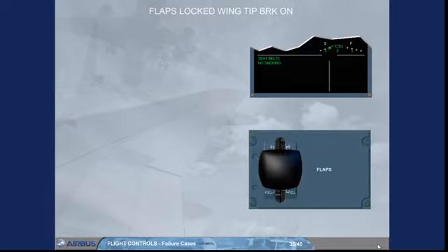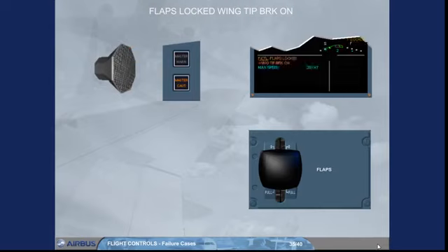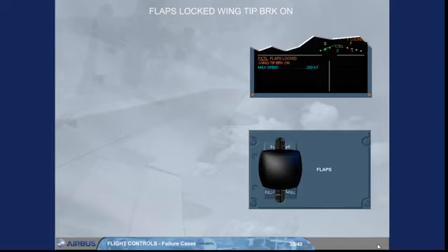Let's now review some slats flaps failure cases. You are in the approach phase. The slats and the flaps have to be extended. You have just set flap 2, but an ECAM caution occurred. On the engine warning display, read the title of the failure.